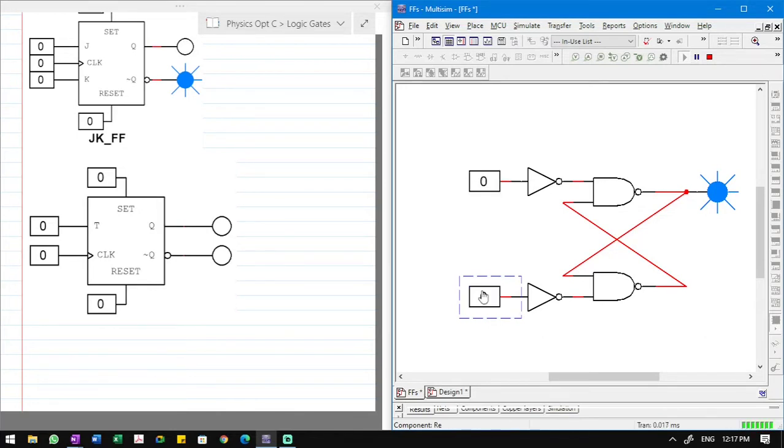However, I could reset this output state over here by using this input below here, which is the input R, right? I took off the ref des and so on. So the output of the circuit is now in the reset state. So R had been used to reset the circuit over there. Again, once you do that, you lose control of it with this particular input. S is now controlling it. So I could now take S and set a bit over there, right? So that is your SR behavior, right?